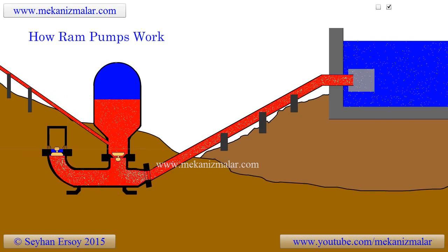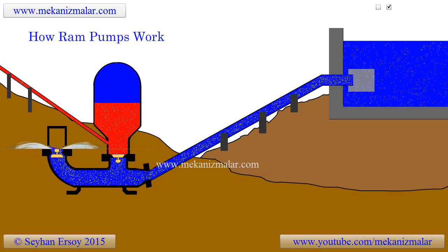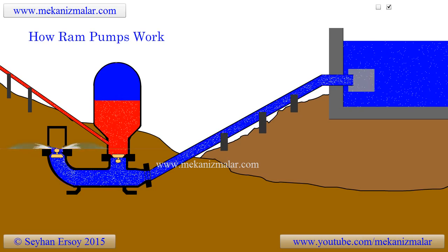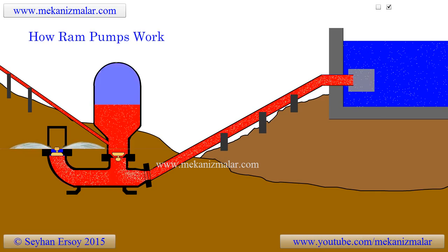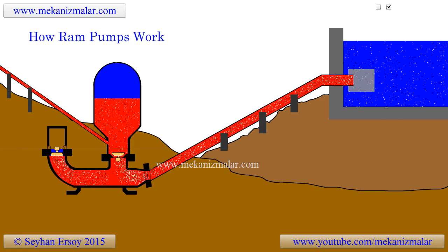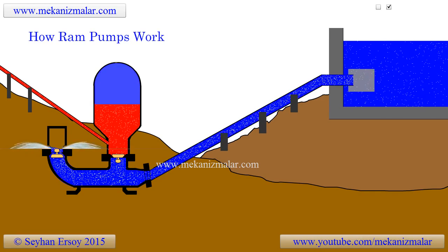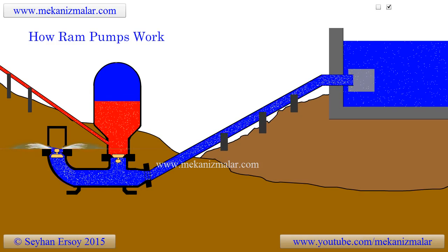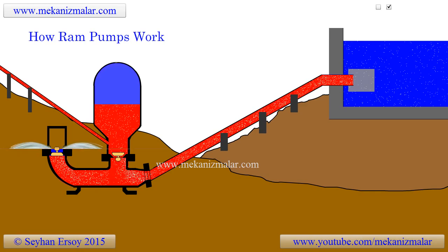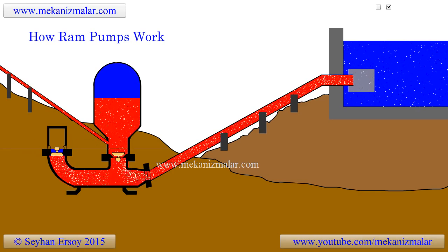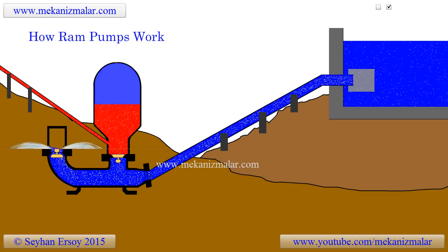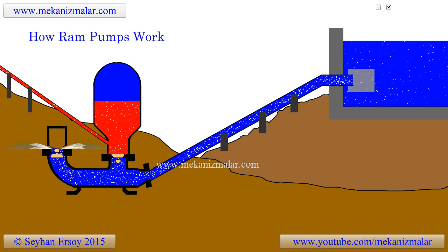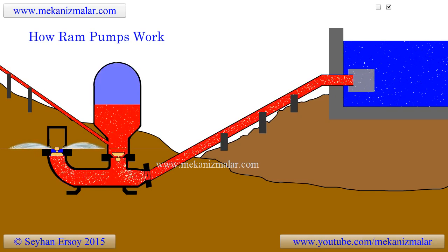The system may seem like it's disposing of too much water, but it's not the inefficiency of the ram pump, but instead the requirement of the conservation of energy principle. If 10 liters of water per second is fed to the ram pump, and 2 liters of water per second would pump to 100 meters of elevation, this would violate the conservation of energy principle. But a quarter liter per second is a darn good flow rate for the system mentioned, and does not violate any energy principles.